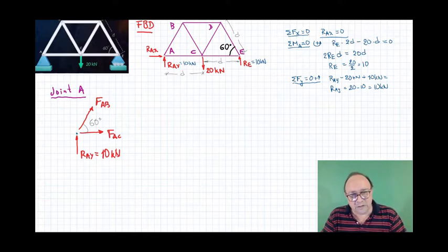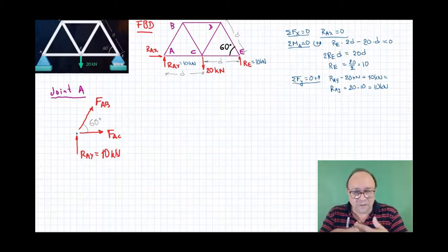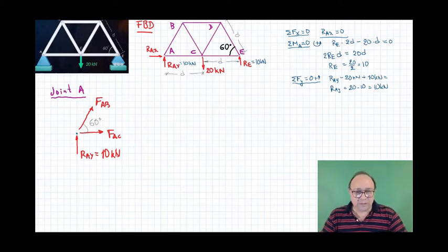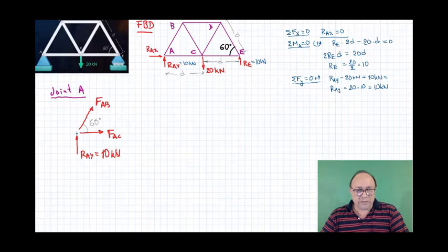So instead of being tension, they are compression. And since they are negative, that follows the customary convention of signs. You find the negative forces are compression, so that's the best way to write it. A negative means compression, and it means that the assumption that you did was wrong.